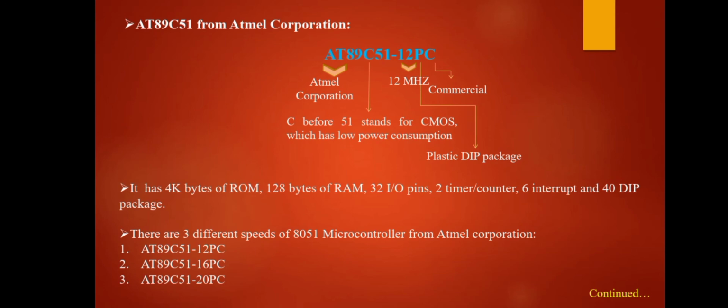12 stands for 12 MHz. It is maximum clock frequency. 89 is a series of variants which Atmel was developing. Here C stands for commercial.